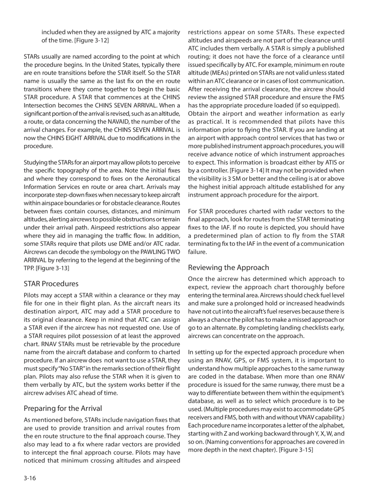After receiving the arrival clearance, the aircrew should review the assigned STAR procedure and ensure the FMS has the appropriate procedure loaded, if so equipped. Obtain the airport and weather information as early as practical. It is recommended that pilots have this information prior to flying the STAR.